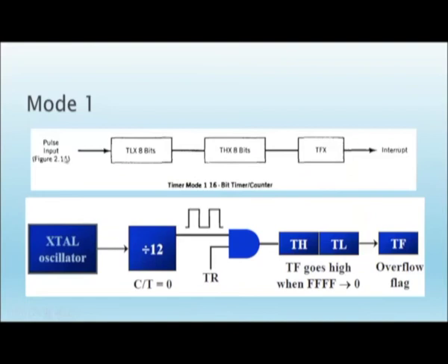The next one is mode 1, in which the pulses given are loaded in the two 8-bit registers TL and TH, both are 8 bits. So, totally 16 bits you can use here. Whenever the overflow occurs from FFFF to 0, then the timer flag is set.